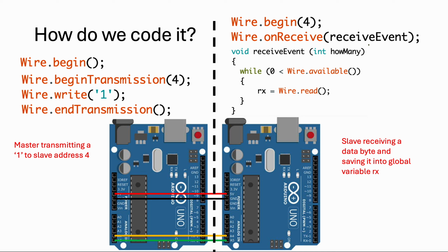There are more instructions depending on master or slave mode that we need to consider. Just writing the most basic ones. Like in this case, we're starting with Wire.begin to initialize this one as a master. The next instruction, if we want to transmit data, we need to write Wire.beginTransmission, and we need to specify the slave address that we want to communicate with.